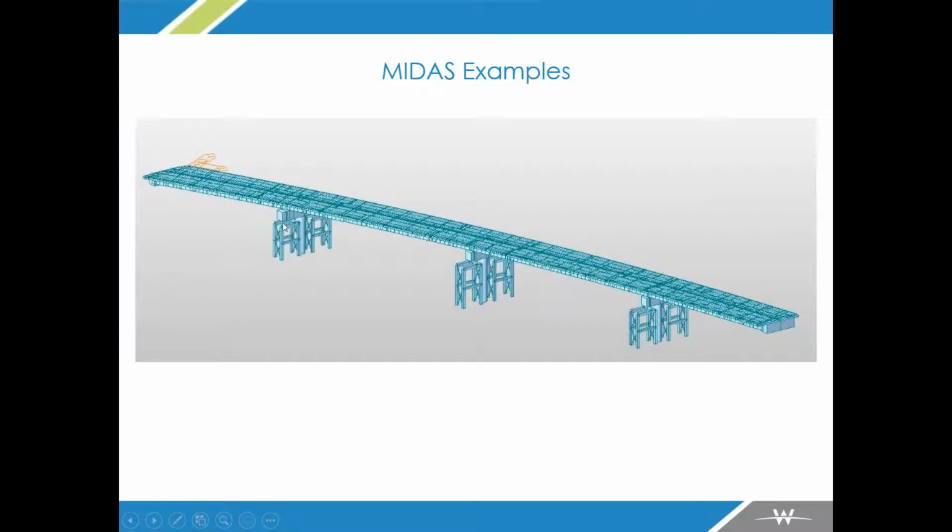You've got a situation where there's a bearing under that, and you need full engagement of that tower. And as that deflects, again, you need to make sure everything's corresponding between the deflection as a cantilever beam of your pier cap and the vertical displacement, basically squishing that tower with axial compression forces. So those have to all work together.